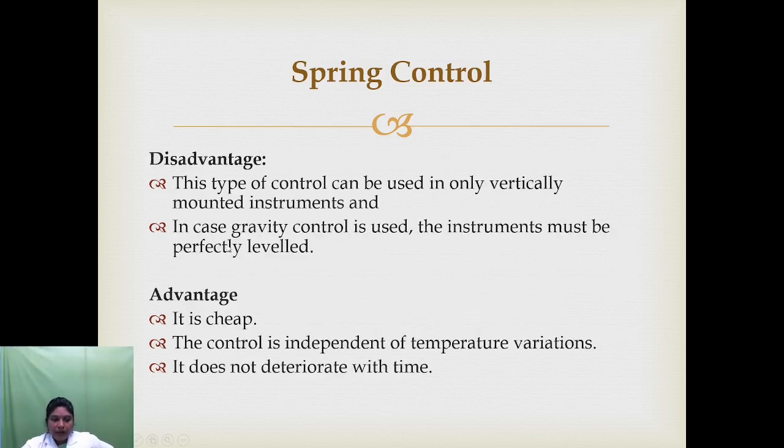So what are the advantages and disadvantages of spring control? It is cheap, the control is independent of temperature variation, and it does not deteriorate with time. So it does not change with time. These are the advantages of spring control. And what is the disadvantage? This type of control can be used only in vertically mounted instruments.